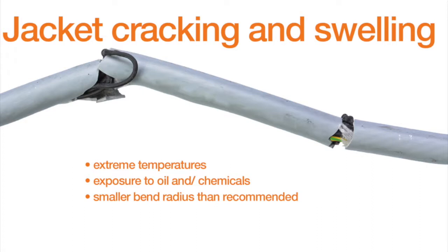So it may not be a noticeable failure at first, but it will lead to other problems later on down the line. And the third cause of jacket cracking and swelling is a smaller bend radius than recommended. And typically, again, that goes back towards the jacket cracking aspect.